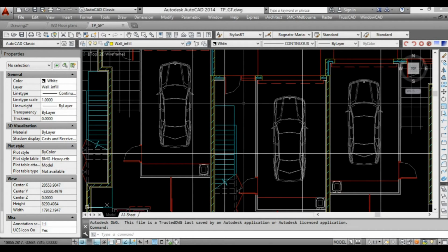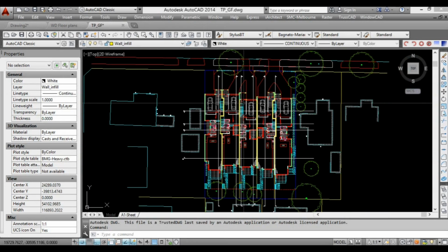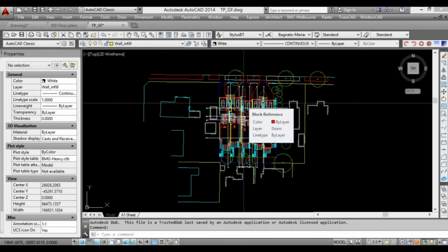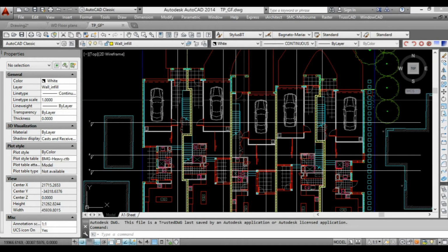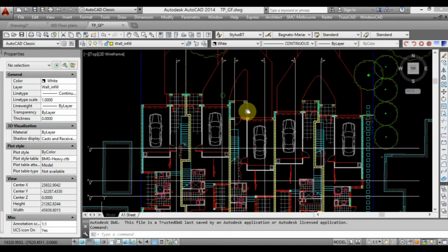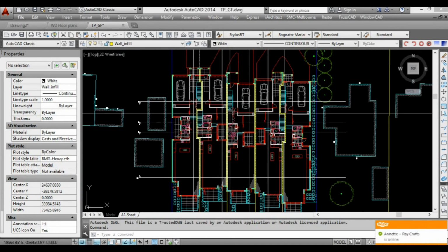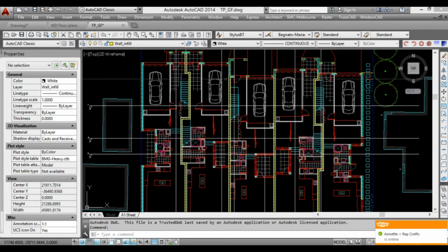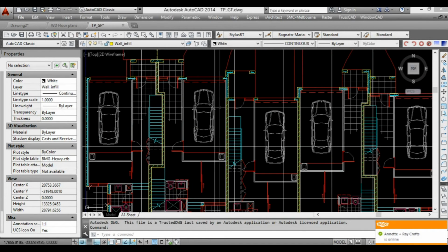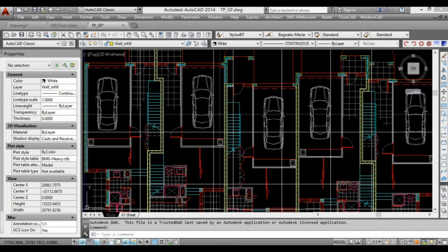And using the same button, this time instead of pressing it down, we can scroll with our middle finger upways, and we'll zoom out, and then downways to zoom in. So that's pretty much the simplest way to move around the AutoCAD screen. You can use a command to do that too, but ever since Autodesk developed the ability to just use the mouse button in the middle, it made things a lot easier. So yep, give that a try.